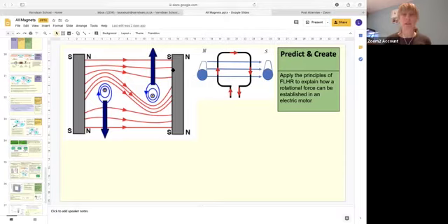They're south-seeking in a permanent magnet. So when we have that interaction between these two magnetic fields, we get this catapult effect here. And what that essentially does is we get the bunching up of the lines, and this then pushes forward in this direction is the force. And we used Fleming's left-hand rule, where this is the force, this is the field, and this is the current, okay? And we were able to predict which way the force would go.